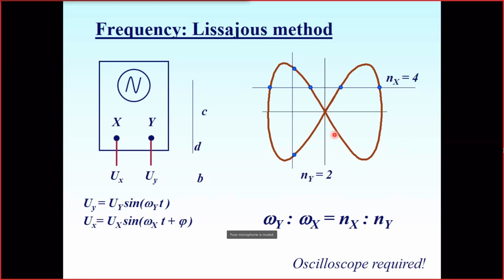The beam moves in the vertical direction and in the horizontal direction. This movement is not synchronized, and that's why we see just a rectangle. All these movements paint over the whole rectangle. Then we start to adjust the frequency of the reference generator, and finally, from time to time, we will see more structured figures, and these will be the Lissajous figures.